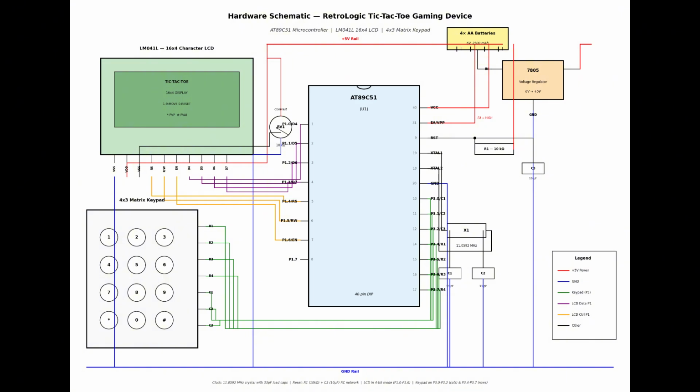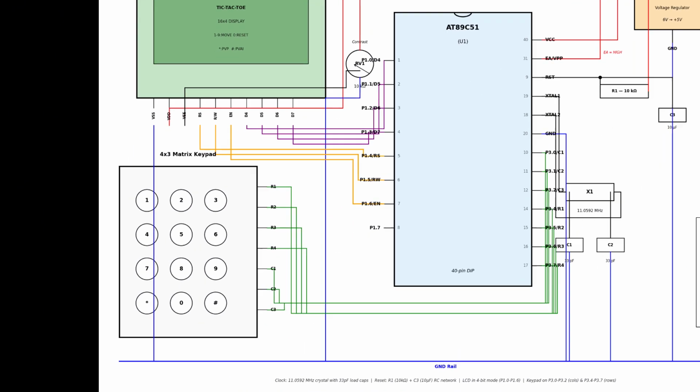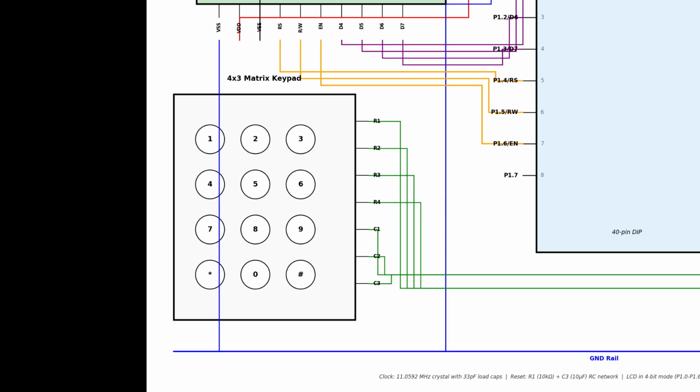The keypad has pre-labeled keys 1 through 9 that map directly to the 9 cells of the tic-tac-toe grid. It requires only 7 input-output pins through row-column multiplexing, compared to 9 or more individual pins for discrete buttons.